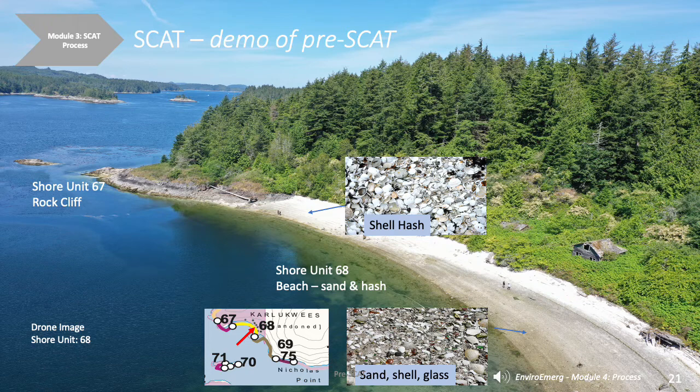If the oil was crude or a heavy residual oil, such as a bunker oil from a vessel, its retention time would be months to years. Owing to this and its cultural significance, shoreline treatment would certainly be a viable consideration. The access and egress to the shoreline is pretty straightforward, as it's a sandy beach with a low bathymetry, but there would be limited space to stage equipment on the shoreline.